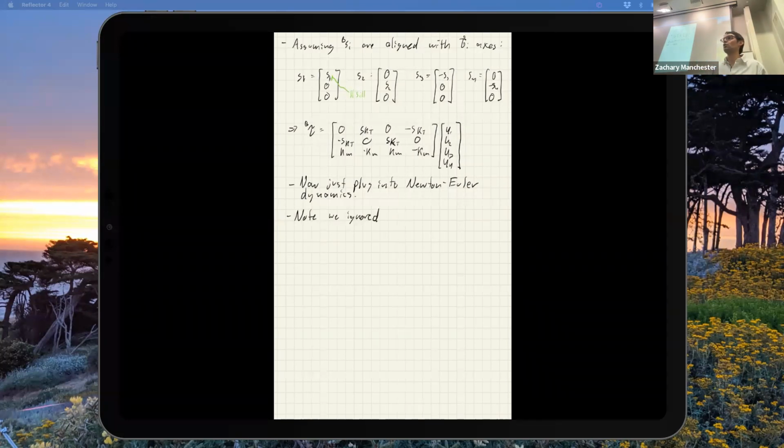Turns out you don't need them. The other fun thing is aerodynamic stuff is all proportional to V squared, right? Everyone knows this. So to first order, it drops out. If I'm near hover, if I'm not moving very fast or I'm linearizing about hover, only the prop stuff actually matters, and it's all proportional to omega squared on the props. And then all the airflow stuff past there is all proportional to V squared, so it all drops out for small velocities. But if I start to move fast, then it starts to matter, right?